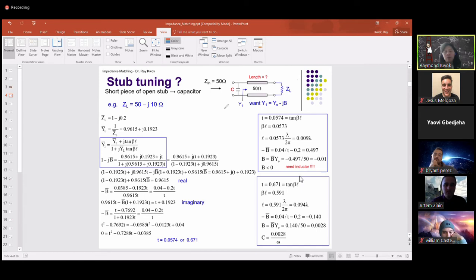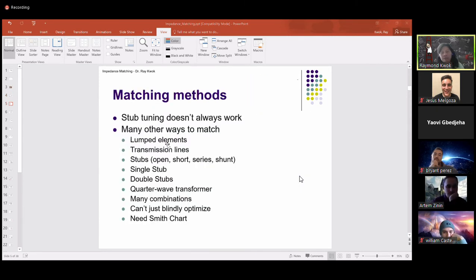All right, so that's one type of tuning. Is that all we need to understand tuning? No, that's just the traditional way to do the tuning after everything is designed and supposed to be 50 ohms, right? And when you put it together, your 50 ohm circuit becomes not 50 ohms because of a lot of reasons. Anytime you have a junction, you break the 50 ohms.